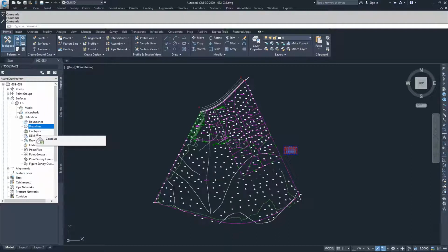If you have a polyline or a feature line or something like that that is set at a specific elevation and you know that line is a contour that has been defined or determined, then what you can do is add those objects into your drawing as a specific contour, and then you can use that line to dictate what the surface is going to look like.